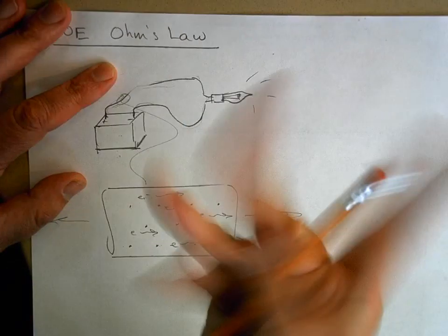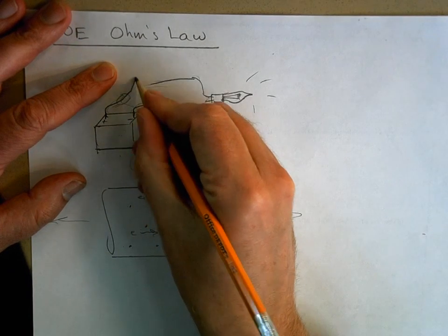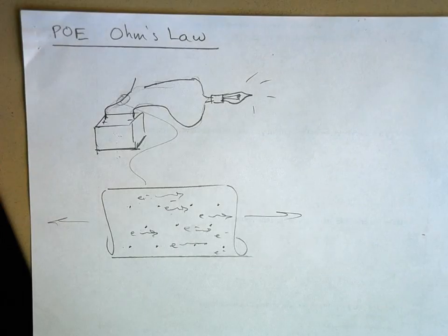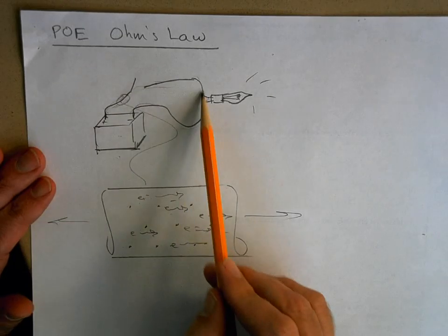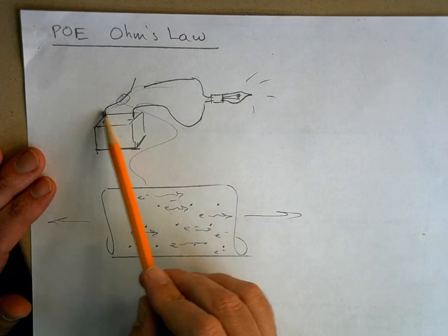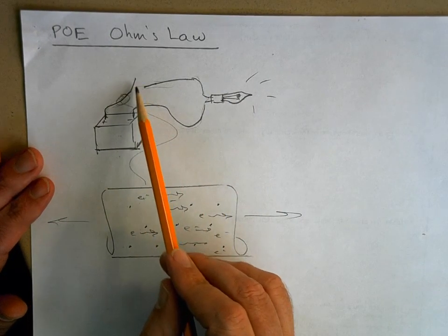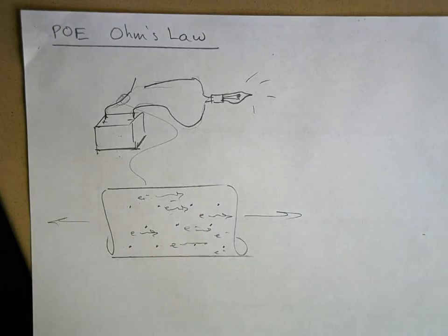So this is the switch that's on the robot. And here's the symbol for a switch. It's just a break in the wire, right? This is called an open circuit. That is, the path that the electrons flow through is open. If there's an opening in your circuit, they can't flow. They can't move. They get stuck.